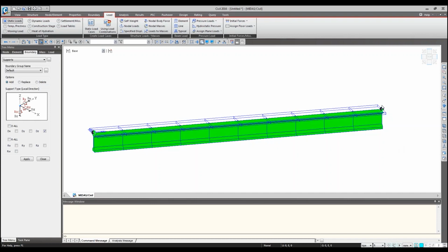And regarding the material, one of the questions that was raised is, so basically in MIDAS, there are two ways to reflect the long-term property of concrete. For steel plate girder composite structure, you have two ways, either by defining the modular ratio 3N method, or by defining the creep and shrinkage functions or the compressive strength function for your concrete. But for steel plate girder, 3N approach is more general. That's also covered in the previous training.